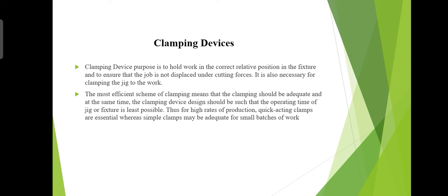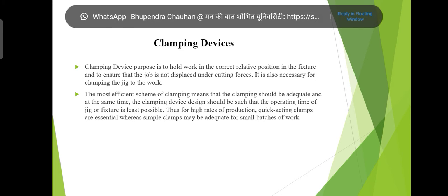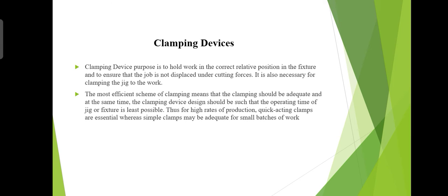Clamps come in a variety of types, sizes and costs, and clamping is the mechanical means to apply force to the part to hold it against the locators. The clamp could be as simple as a bolt that is threaded through a hole in the part and tightens the part against the frame.